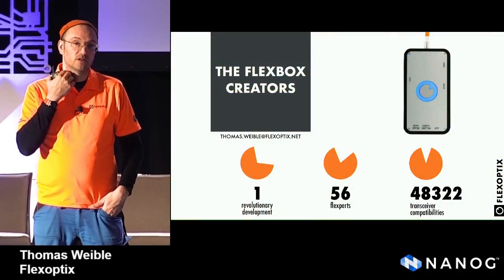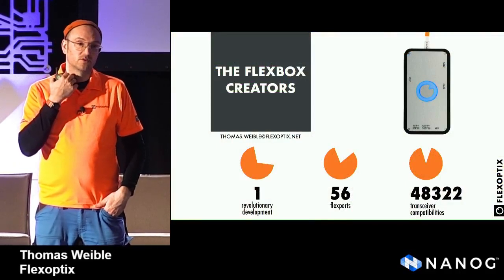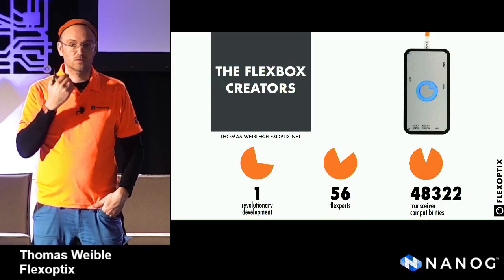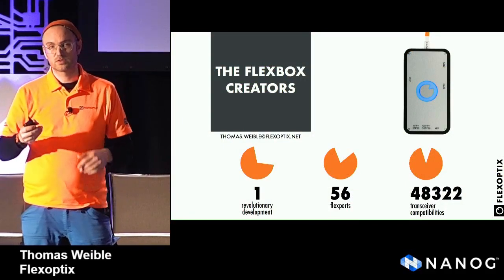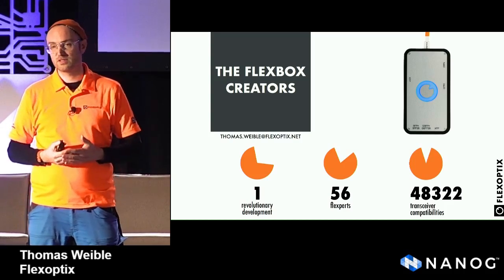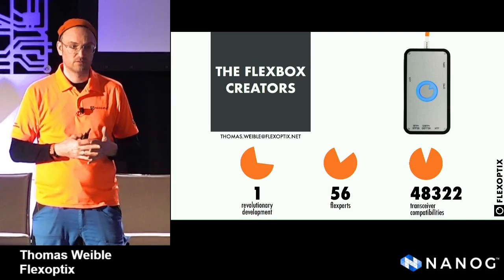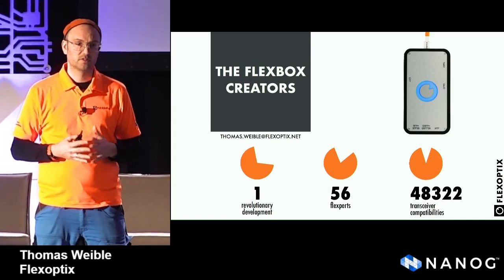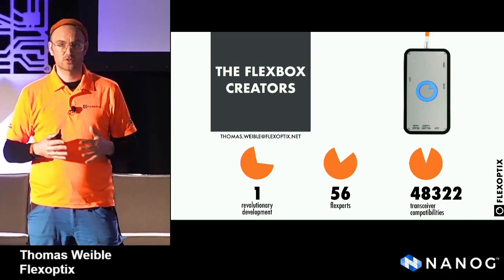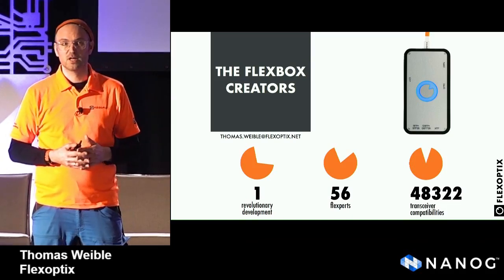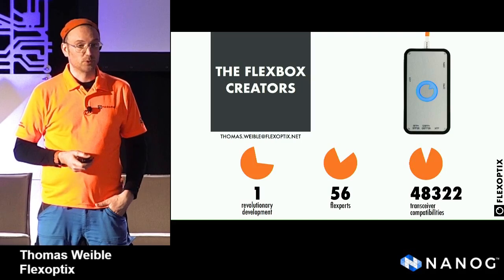For us itself, especially the DSP and the 400 gigabit transceivers will give a new challenge, also when it comes to the implementation of the Flexbox, how we change the behavior of a transceiver. So far we are familiar with the microcontroller inside of a transceiver, and now with the 400 gigabit this will be a little bit game changing, because also the DSP is running a firmware, is running a configuration, and needs to be tweaked and optimized.